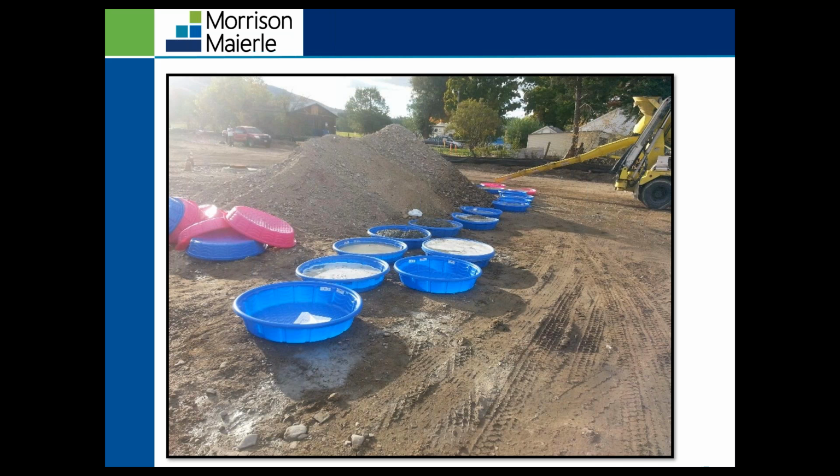I know that I'm an engineer, I've been on construction sites, I'm a SWPPP administrator. I've seen how it is with a lot of these, is that they wash out right where they're pouring the concrete. So if there's no way of containing that, that wash water can then enter the aquifer. And then with this BMP, you want to make sure that you are disposing of the concrete once it cures.